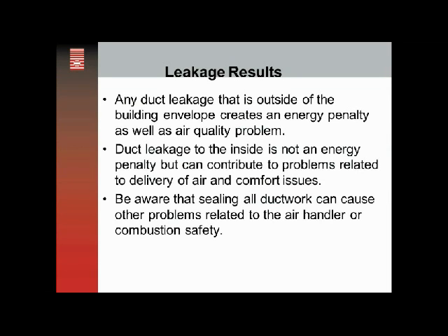Any duct leakage that is outside of the envelope certainly creates an energy penalty, as well as an indoor air quality problem if you've got return leaks that are sucking air through loose fill fibrous insulation. Duct leakage to the inside of the building may not be considered an energy penalty, but it can certainly contribute to problems related to air delivery, comfort issues, and be aware that sealing ductwork can create other issues,